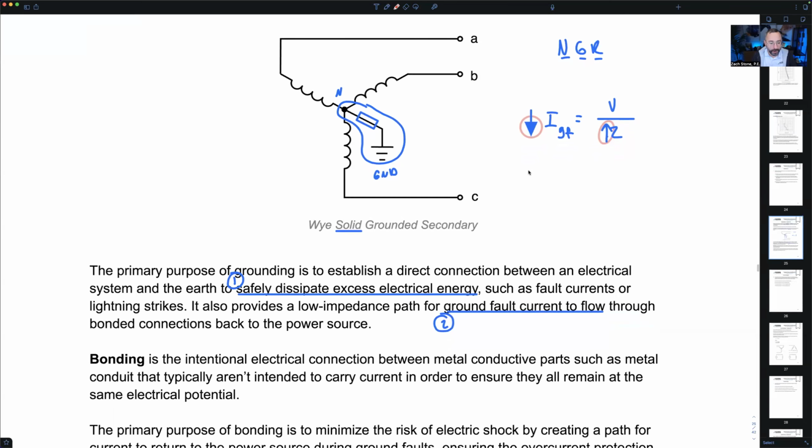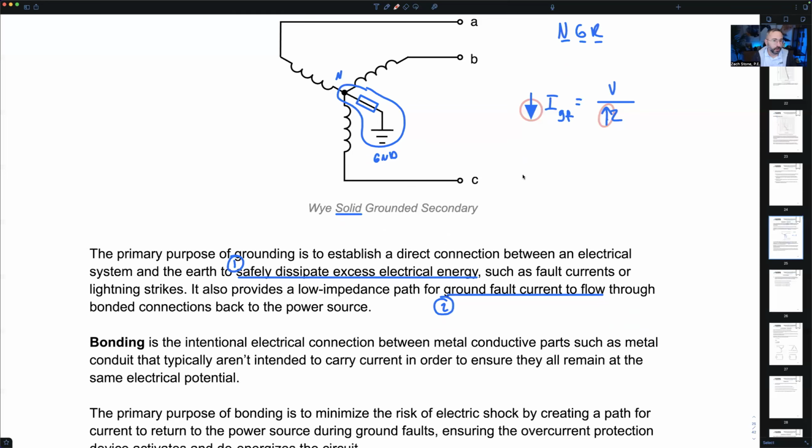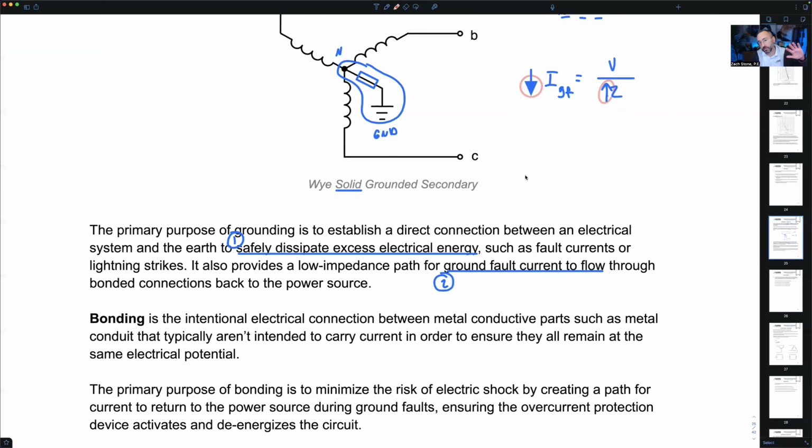All right, so how about bonding? What's bonding? Who here has ever swapped out a receptacle at your house, maybe a new light switch? Who here's done any minor wiring? You're getting your hands on the wire nuts, making sure the power's off, all that good stuff. Maybe you replaced the ceiling fan in your office, like I did. Anytime you've got that bare metal equipment grounding conductor and you land it on the exposed metal parts, that's bonding.